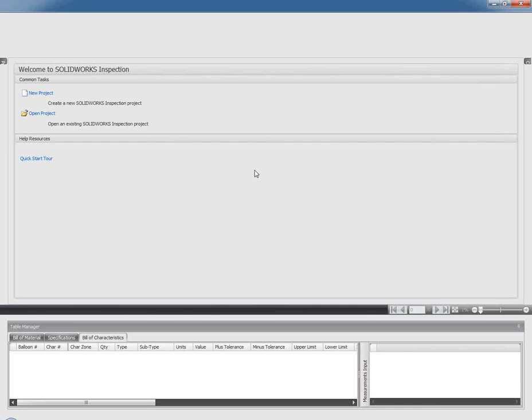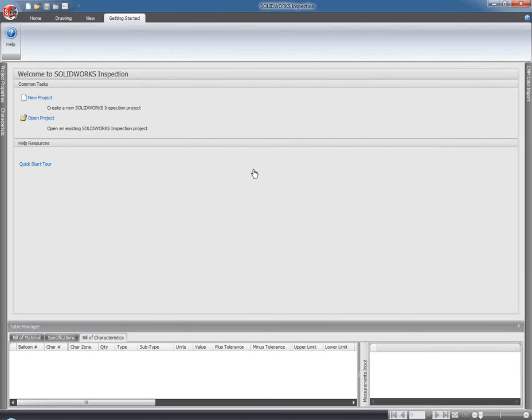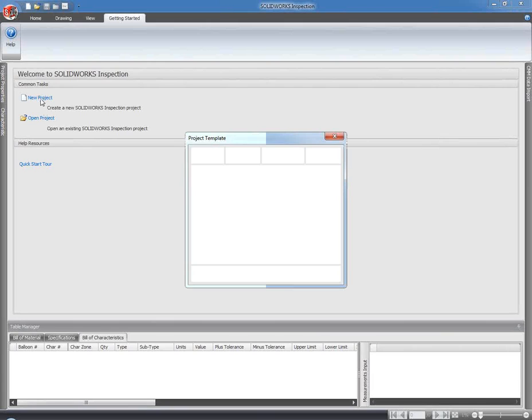Now, if the overarching philosophy with the integrated SOLIDWORKS Inspection is that you take a wholesale approach and you remove the items that you don't want, the overarching philosophy with the standalone application is kind of opposite. Because TIFF files and PDFs don't have any real intelligence to the text that appears in them, this standalone application makes heavy use of optical character recognition. And you're going to see in a second here that we get the opportunity to window around various dimension values that show up in the PDF, and then using OCR, optical character recognition, SOLIDWORKS Inspection will extract out the nominal value in addition to any explicit tolerances that exist. The extraction characteristics or the project characteristics are somewhat the same as what we saw before. So let's just get into it so you can observe the similarities and the differences.